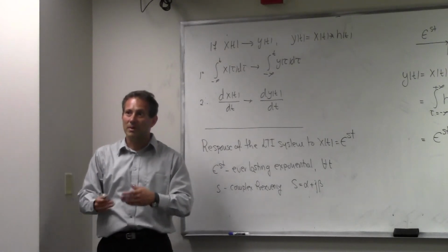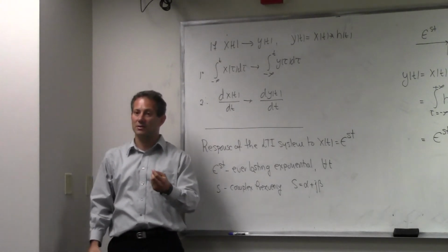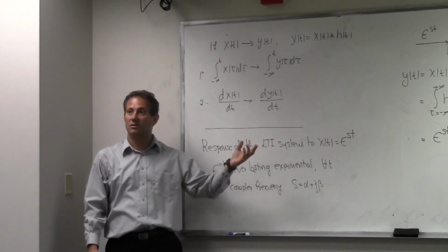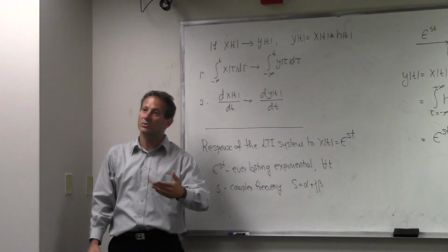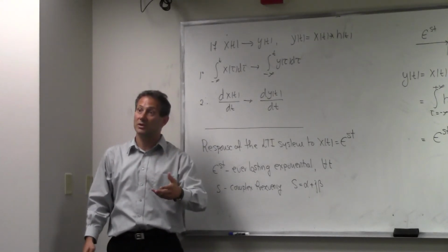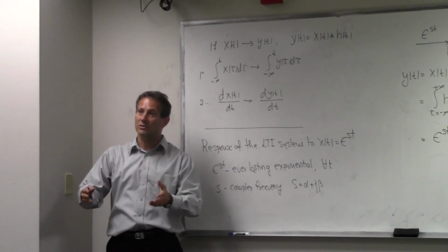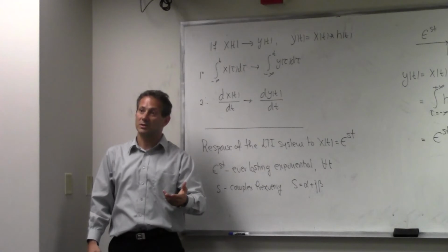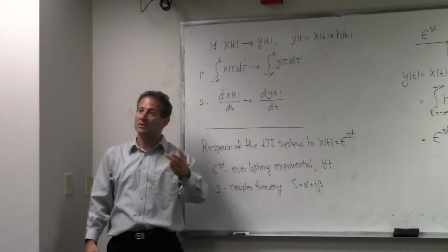One of the common methods we use to characterize the linearity is through tests where we feed in tones. There's a single-tone test, two-tone test, three-tone test, where we actually feed in individual sinusoidals, and then we look at the byproducts: do I have mixing of them?